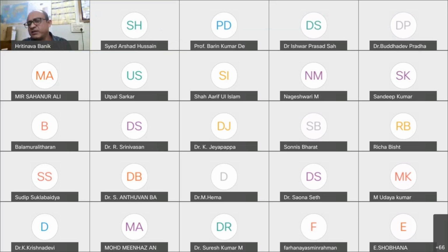Wilhelmy plate. What is a Wilhelmy plate? This is a simple plate. You can use, say, a copper plate or a filter paper like this, because the Wilhelmy system is mainly a technique to measure the surface tension. So anything you can use, a simple paper. If you want to know the dimensions, you dip it into the surface, and it will be connected with a balance.